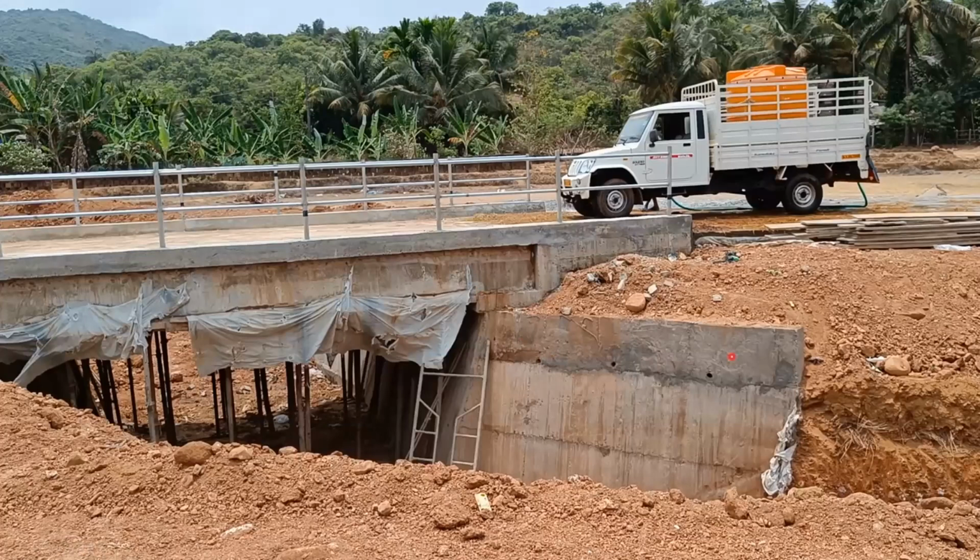And then we have kept these, which are called weep holes. So why are they called weep holes? Because you have done a lot of backfilling. When I've done a lot of backfilling, during the rainy season there will be water in the moisture, right? If there is water in the moisture, it has to pass through, right? If you don't give these weep holes, what will happen? It will create a lot of pressure on this wall. So I don't want that pressure to be created. So what I do is give this kind of holes here.